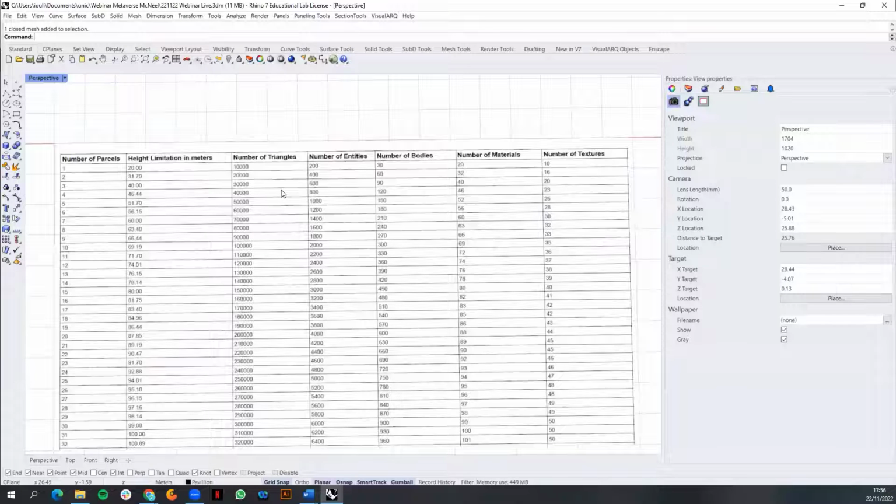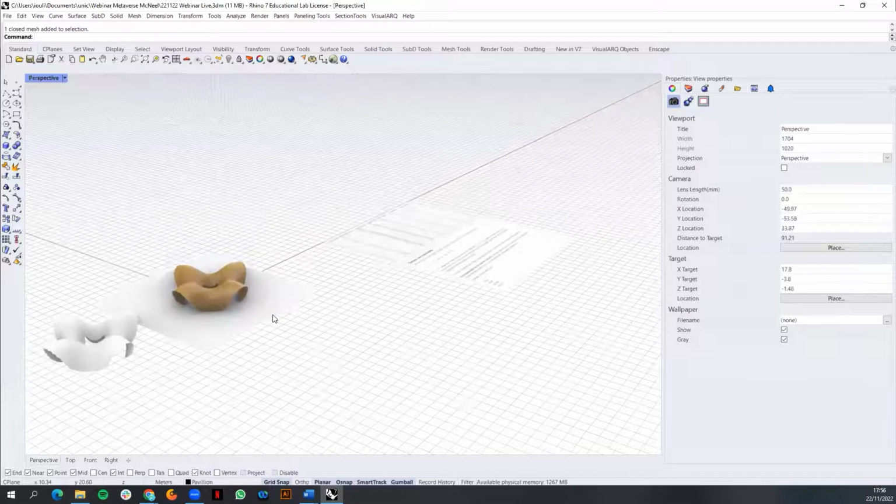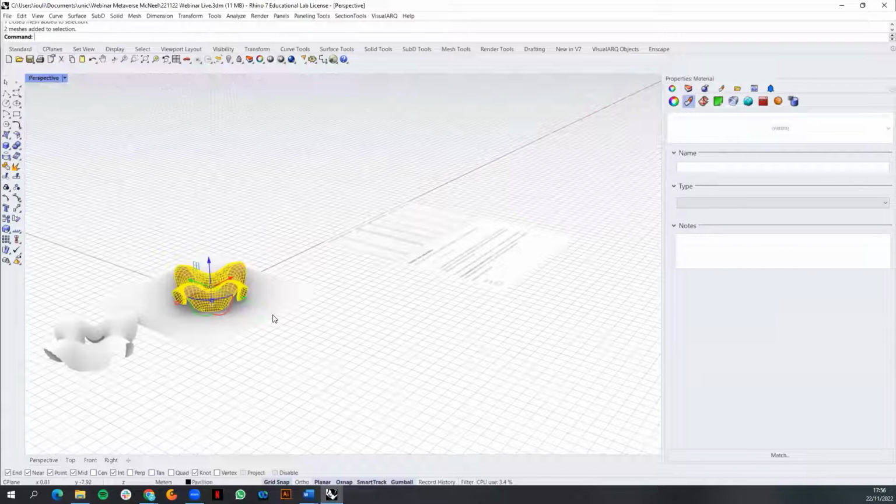To determine that from your model, you select any model you have, and you run the polygon count command. That's a forced triangulation, basically, which will tell you that if you export this to Decentraland, it's 7,500 triangles. I don't know if that answers the question, but that's what I understood. I'm sure it did. Yeah.